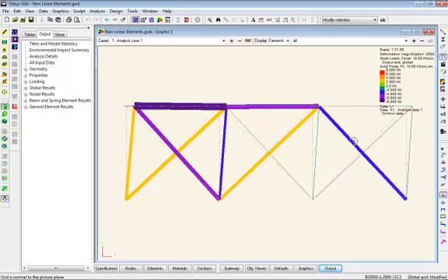Now these are non-linear elements in that when it runs the analysis, it's iterative. GSA will determine which tie is in compression, switch it off, which strut is in tension, switch it off, and then rerun the analysis. It's possible that the analysis might oscillate between two states and therefore not converge. So it's something to watch out for. Not too often, but it can happen.